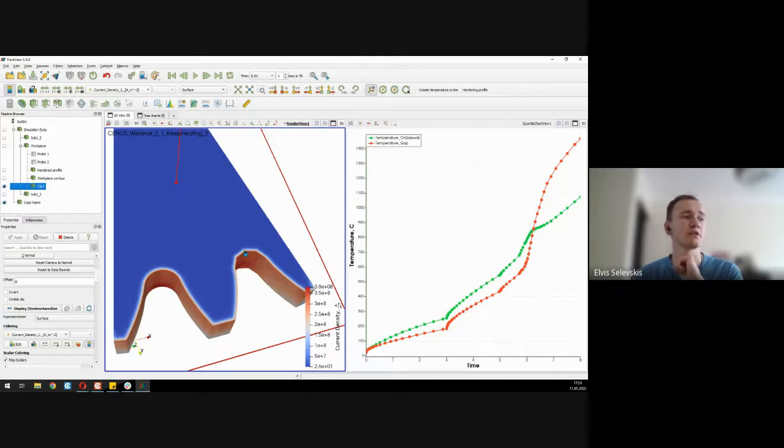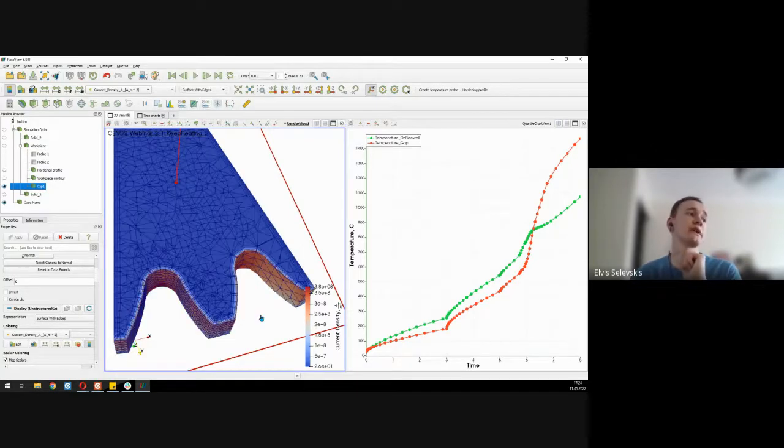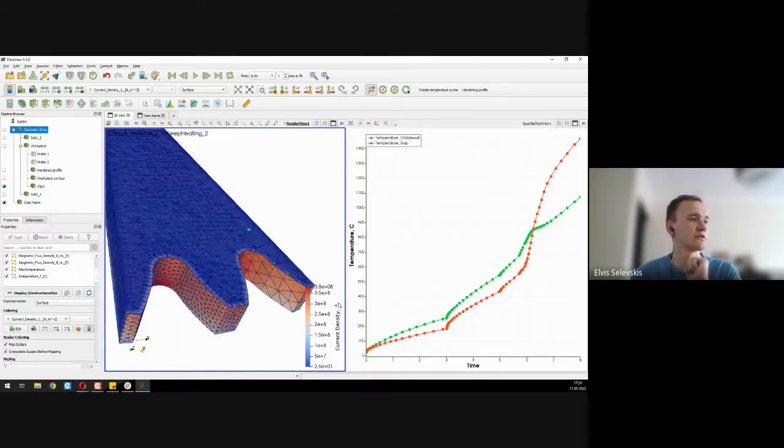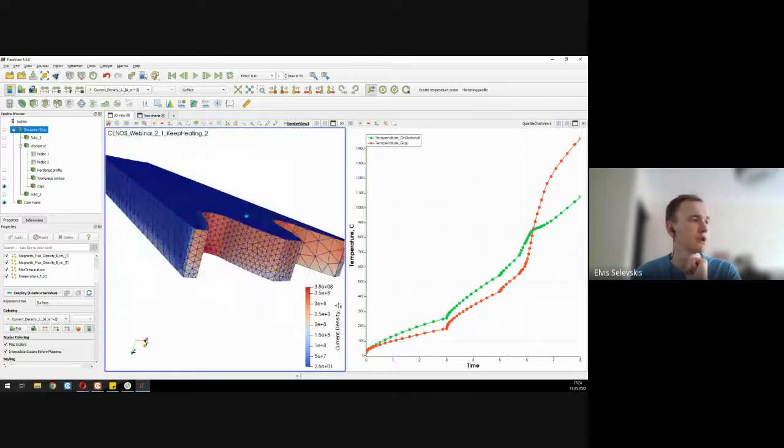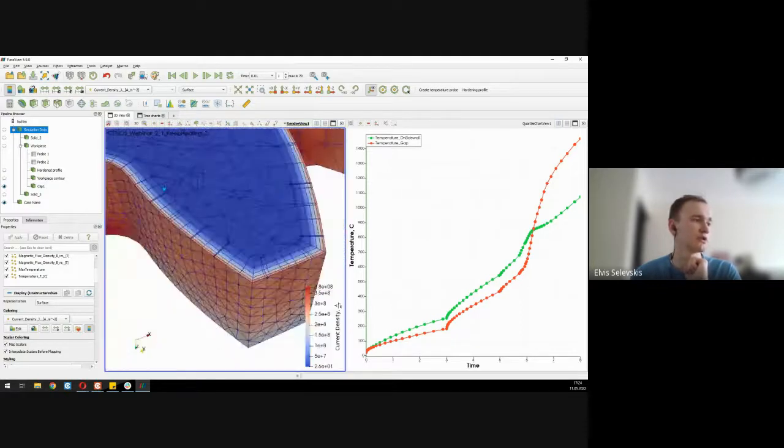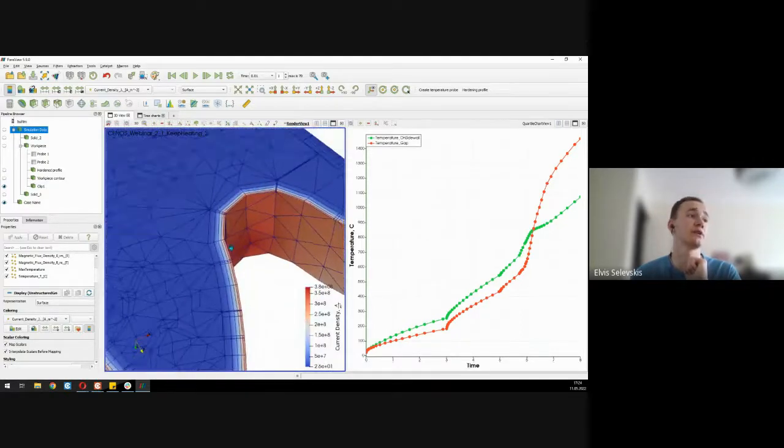To even see our viscous layers on this clip, we can enable the visibility of surface with edges. And right now we can see how the viscous layers actually look and if they are sufficient enough. Now I will click somewhere else just so we don't move the clip around, and we can zoom in on the viscous layers and see how they are doing.